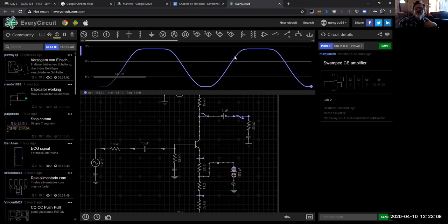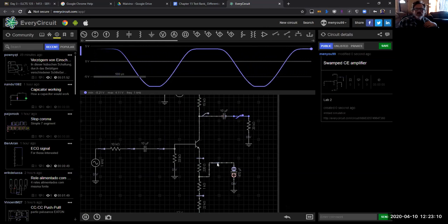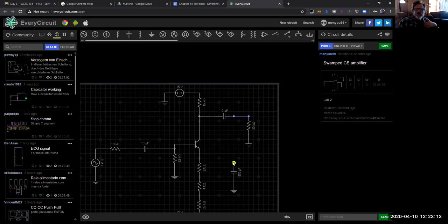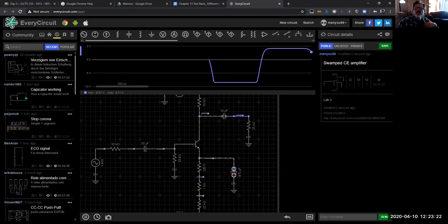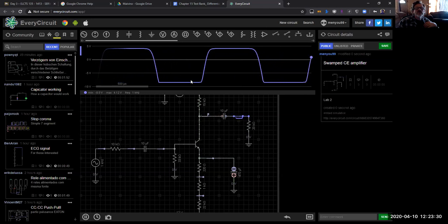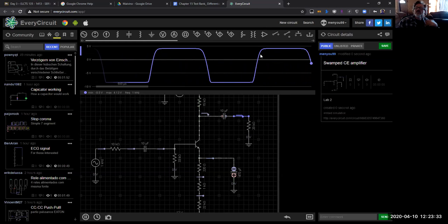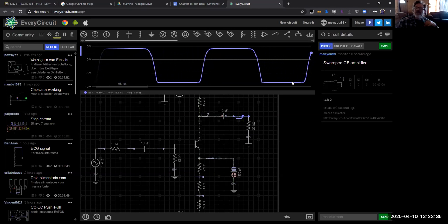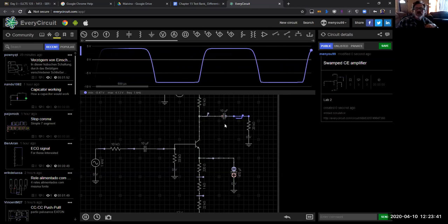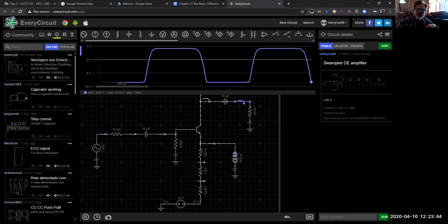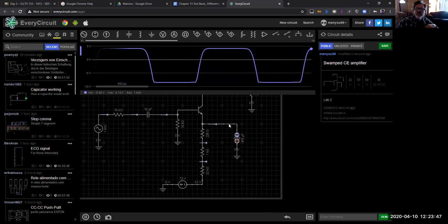But again, we don't really have any distortion effect. Let's look one more time and put it back to the original position. Now let's take a peek. Again, we are getting severe clipping. Notice our regions here, and that's our limits. If I did want to make something with a timing effect or a pseudo square wave, that would be something to go with. But yeah, the orientation of that capacitor does matter a lot.